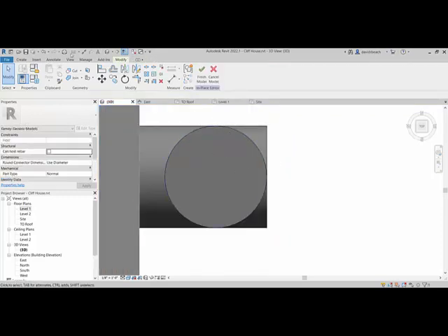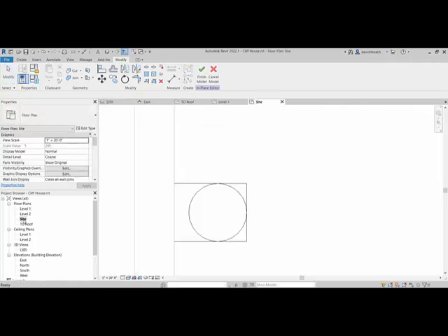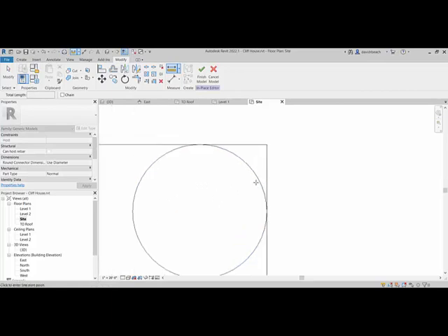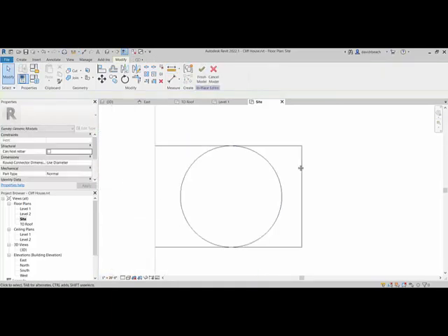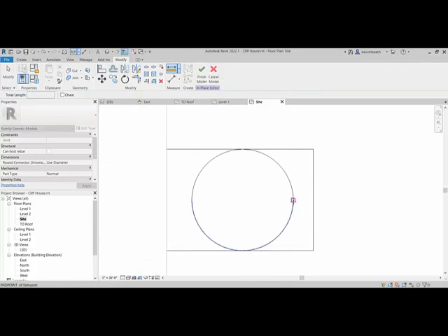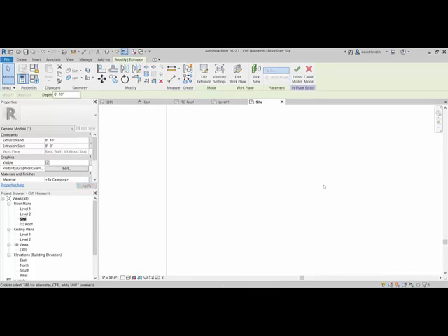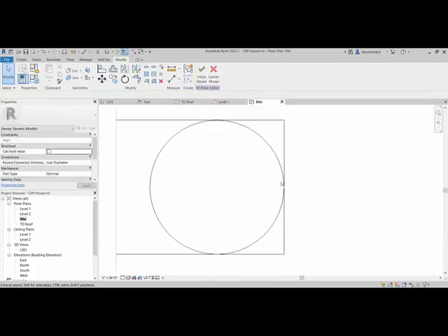And that number, if I look at my site plan and run a very accurate dimension, outside edge of circle to the wall is 10 inches. I need this actually set to 10 inches so that I can grab the end point of that cylinder, draw a line in 8 inches, and then down at 45.